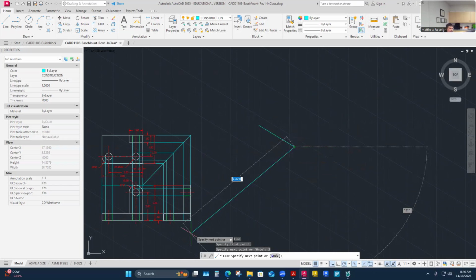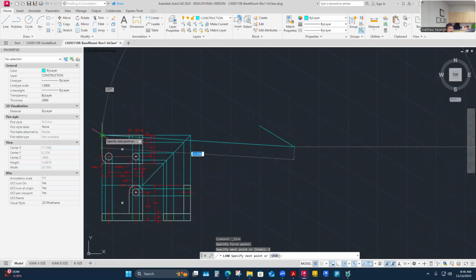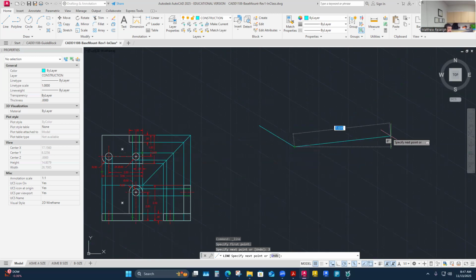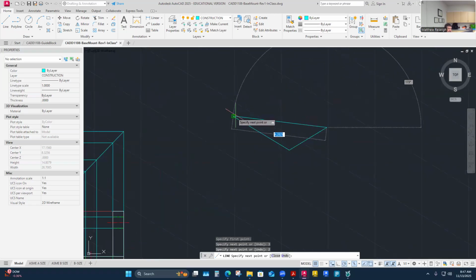And so I might just draw the base footprint for this object on 30 degree planes. I want this to be 30 degrees from horizontal this way. And I'll make it a 90 degree little corner in from where this line is starting. The overall depth of this was 2 inches, right? Yeah, 2 inches this way. So that's the full scale nature of this. I'm drawing this at full size, full scale.